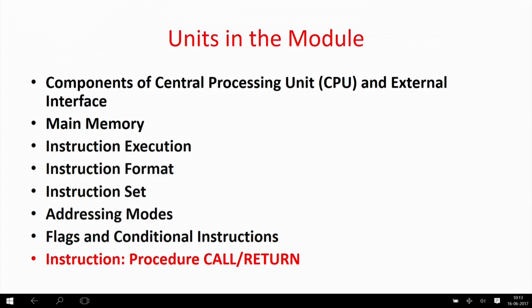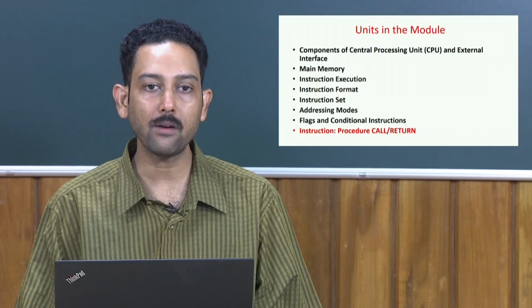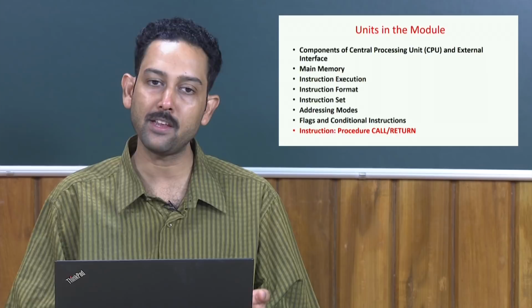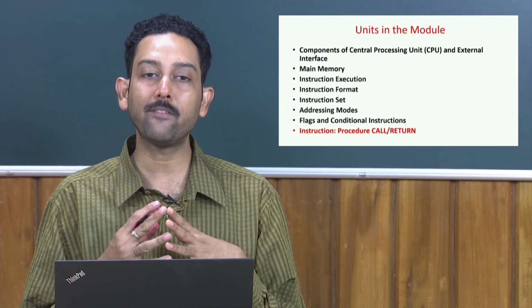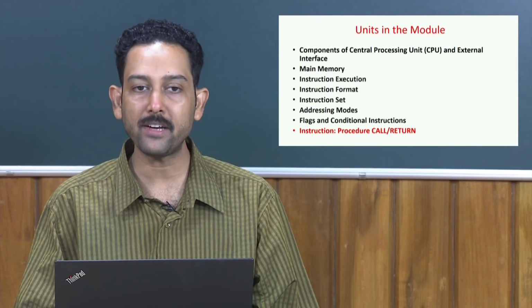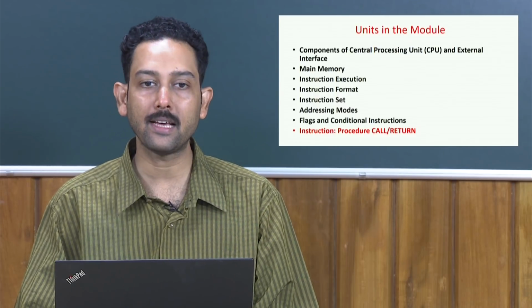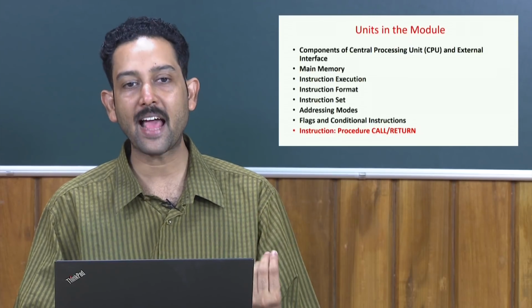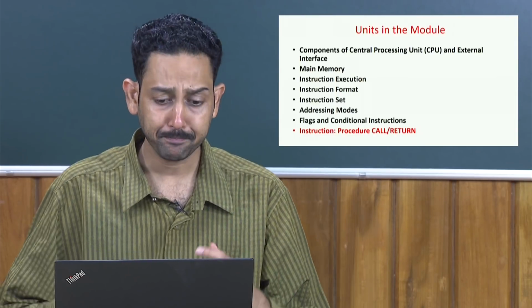some conditions of variables like the zero flag or other conditions like equality, parity, etc. We can jump to a required memory location to execute the instruction from that point, or if the condition is not true we can just go ahead to the next instruction. And then we had seen that flags play a very important role in control instructions. Flags are register bits which are set or reset depending on the conditions of some mathematical or logical expression. For example, if you add 2 numbers and the answer is 0, then the zero flag is set. Then you can use a conditional instruction called jump on zero using that flag bit.